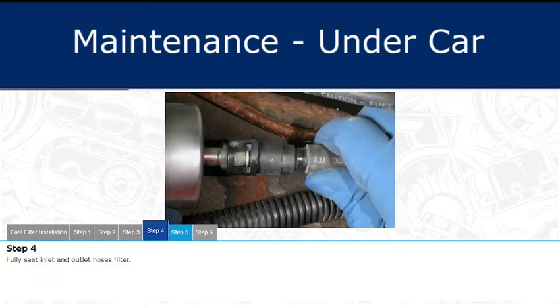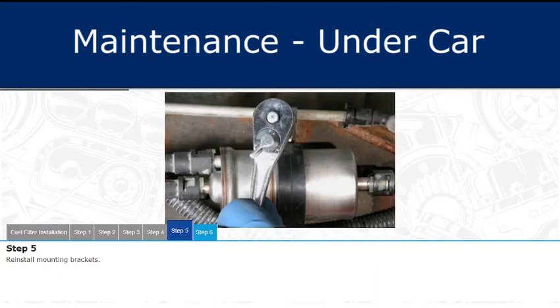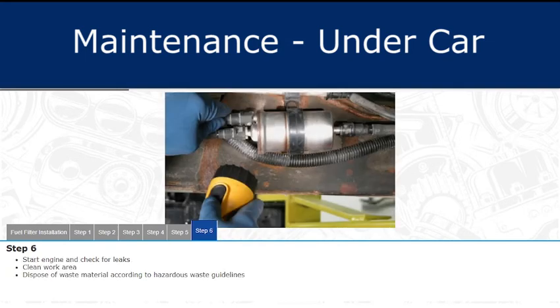Fully seat the inlet and outlet hoses on the filter. Reinstall any mounting brackets. Start the engine and check for leaks. Once the filter installation is complete, clean the work area and dispose of any waste material according to hazardous waste guidelines.